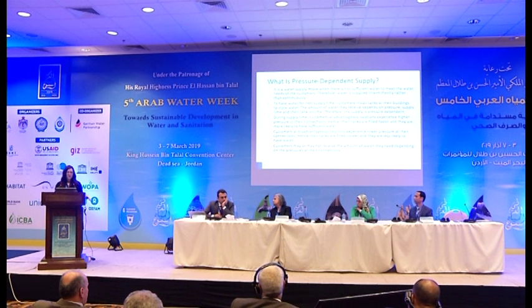During supply times, those customers who are at advantageous locations, like low areas or close to the supply source, can fill their tanks, while customers at disadvantageous locations will suffer from poor supply due to the low pressures at the connection points. So they may not be able to fill their tanks for the required supply over a week.